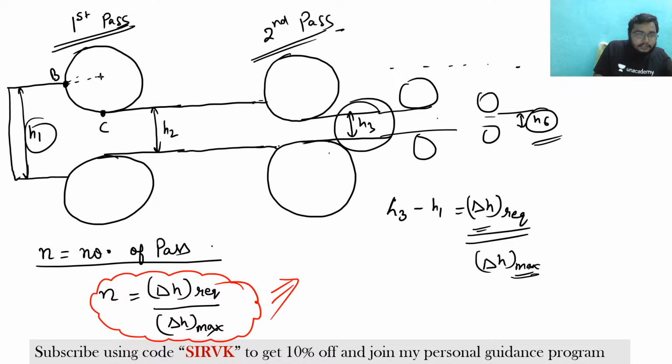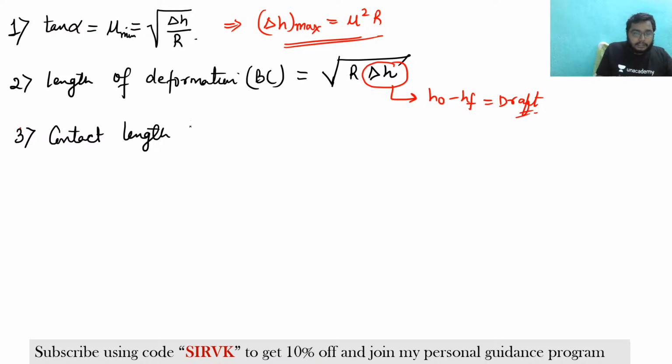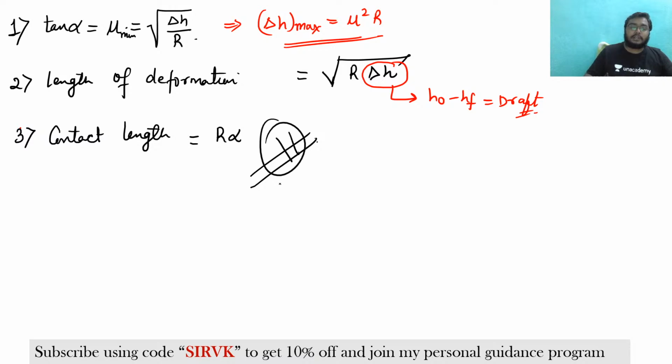So if this is the condition, this BC is the contact length, this is R, this is alpha, so BC would be R alpha. Just write it here: contact length is equal to R alpha, and the length of deformation is equal to root over R delta H. Now if you can remember these formulas, definitely you can solve each and every problem.